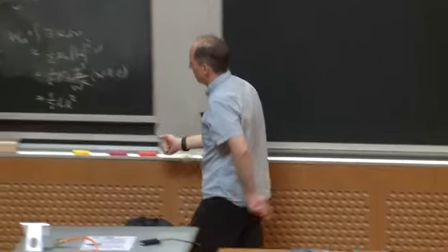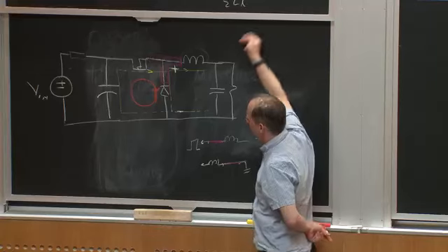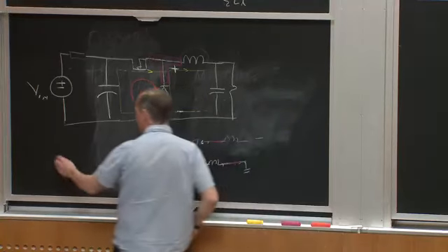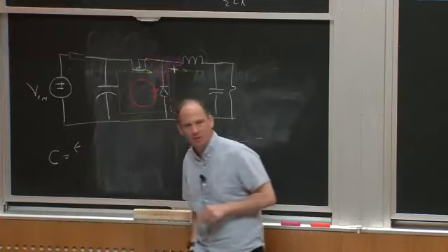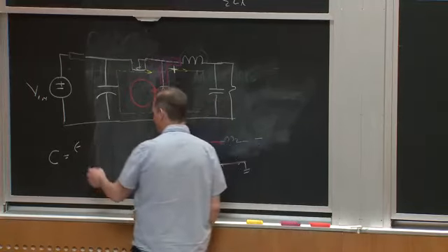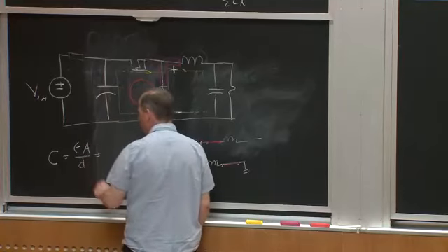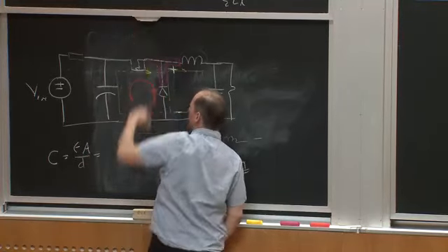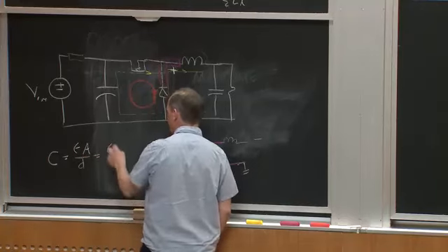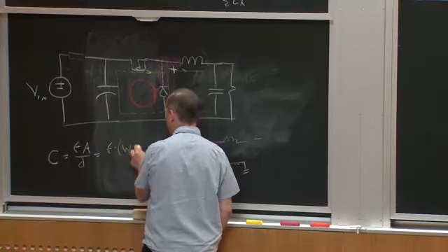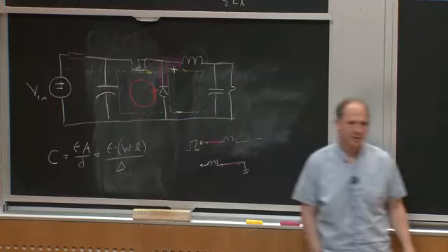That, I think, is more familiar to people. People will recall that the capacitance is equal to epsilon, the dielectric between my two pieces of metal, times the area divided by the distance, epsilon A over D, which with these two plate sizes would be epsilon times the area, width times length, divided by delta. Does that make sense?